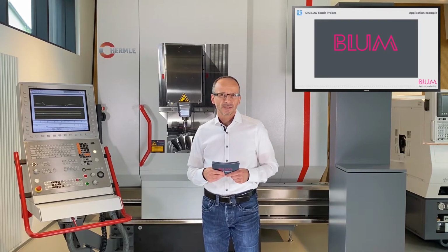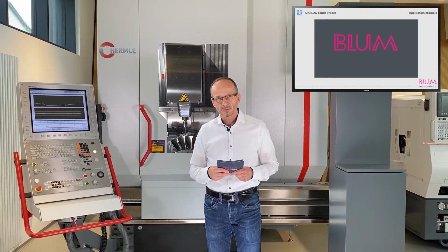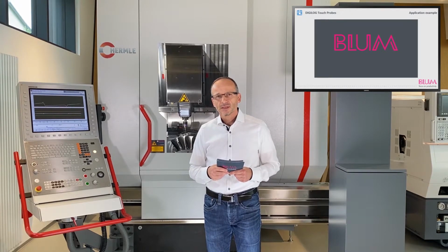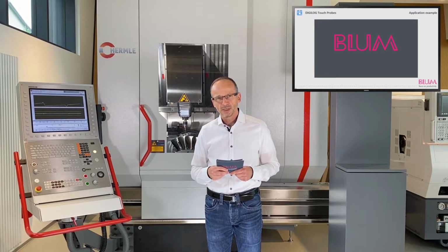The master curve is recorded parallel to the scan. Software for evaluating the measurement data is integrated directly into the machine control. The results are visualized directly on the control screen. We also offer alternative solutions if, for example, full integration of our system into the machine control of older machines is not possible. During production, the components are scanned after the machining process, and the respective actual profile is compared with the data of the target profile.